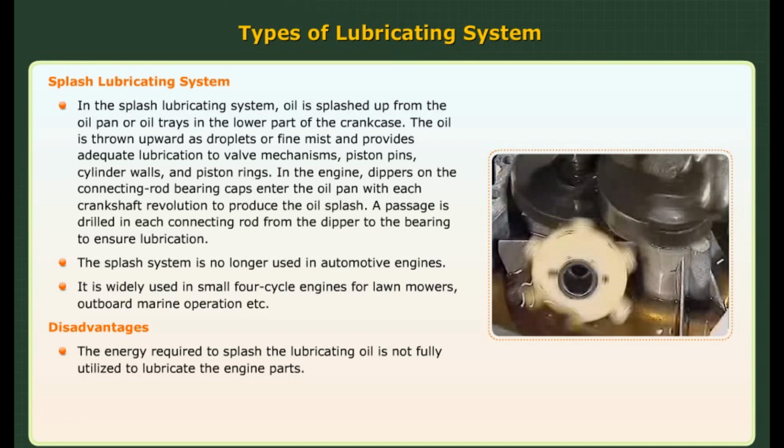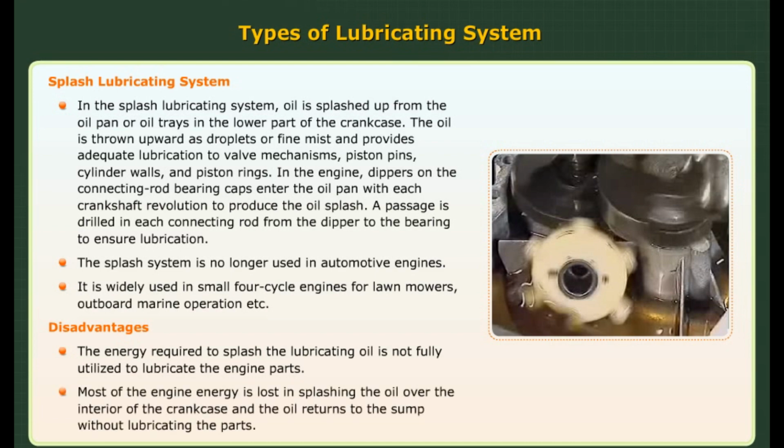Disadvantages. The energy required to splash the lubricating oil is not fully utilized to lubricate the engine parts. Most of the engine energy is lost in splashing the oil over the interior of the crankcase, and the oil returns to the sump without lubricating the parts.